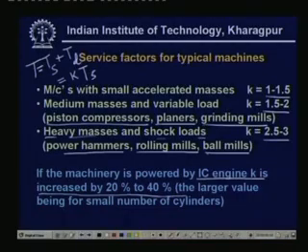So, there is a large power stroke, here the force is very large, and in another stroke there is a small force also, but in 2 other strokes there is practically no force. So, therefore, whenever we have IC engines, then the fluctuation in the torque is very large. Therefore, in case of IC engines, we have to increase K by a factor of 20 to 40%.